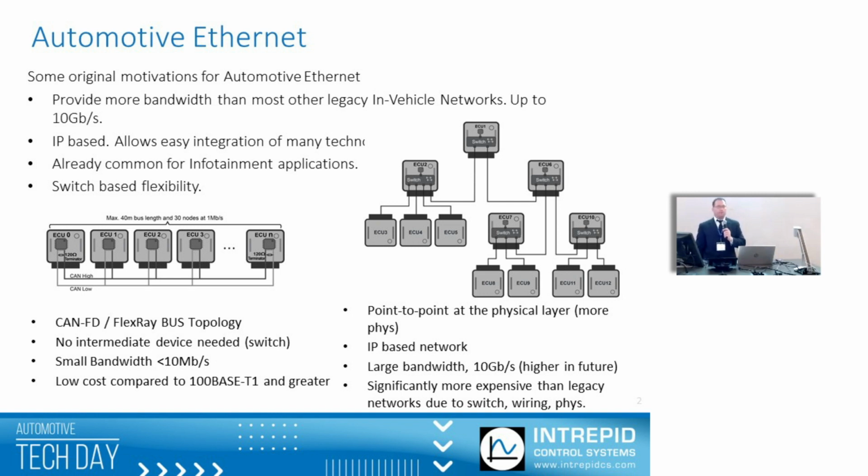And so that was one of the big limitations of Automotive Ethernet, is that the flavors, except for 10BASE-T1S, are all point-to-point physical layers, which means if you want to connect more than two nodes together, you have to have a switch or a bridge. And that brings in a lot of cost just with the switch or the bridge. Plus, additionally, we'll see point-to-point networking causes problems with the length of wiring, connections, and number of physical layers, PHYs, on the network.